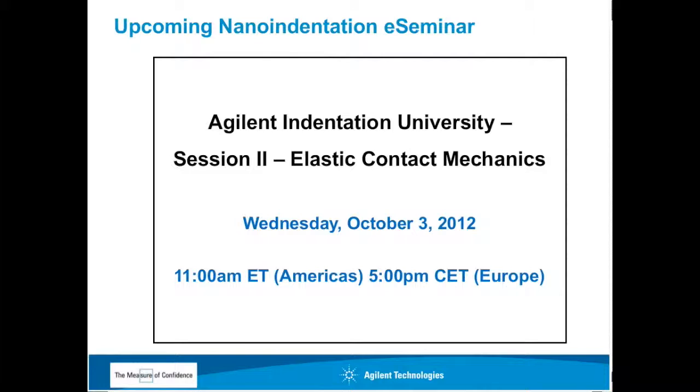But what you have to think about is how that stress relates to the components of stress in a simpler geometry. And that's really the challenge of instrumented indentation. You can't just say how does hardness relate to stress. Hardness is itself a stress. I mean, that is what hardness is. It's a stress. But how that relates to components of shear and normal stress in, say, an infinitesimal square is not easily addressed.